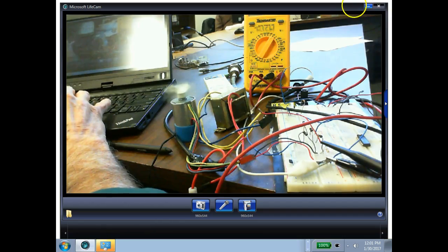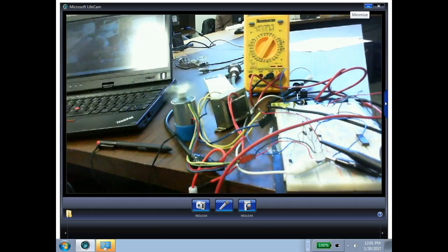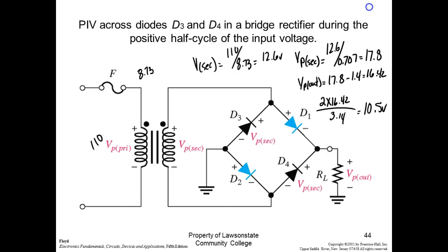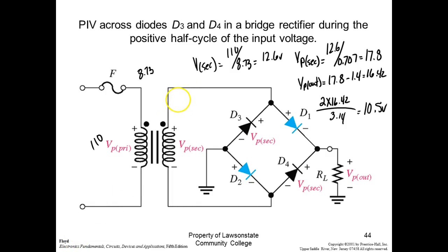That's a pretty good power supply. Another thing, guys, you need to make sure about the size of the resistor. We're putting 10.5 volts DC on this, right? So let's make sure what size resistor we can use. So always check that. So power of the resistor is going to be equal to 10.5 squared divided by 1K. Always check that.